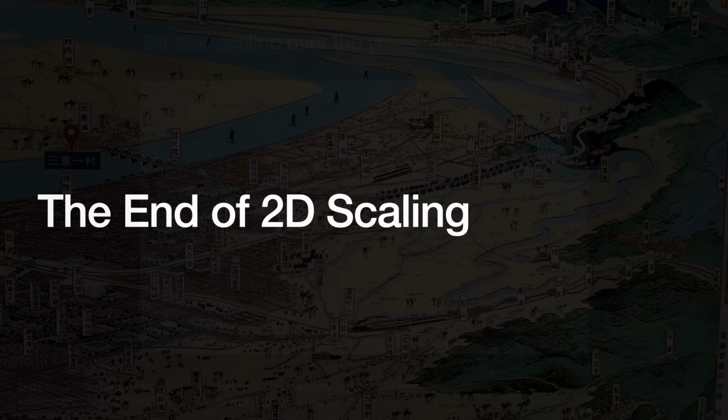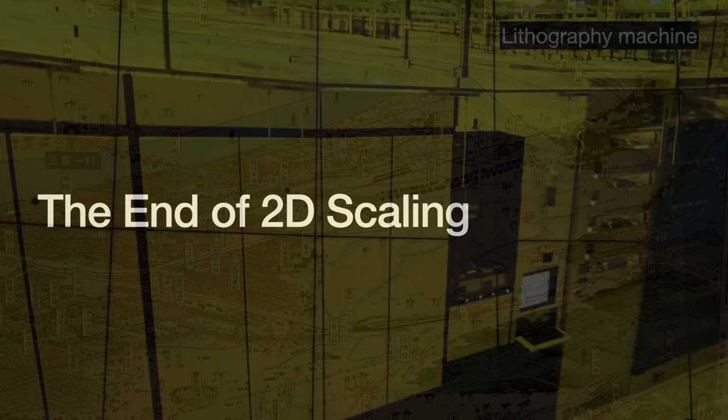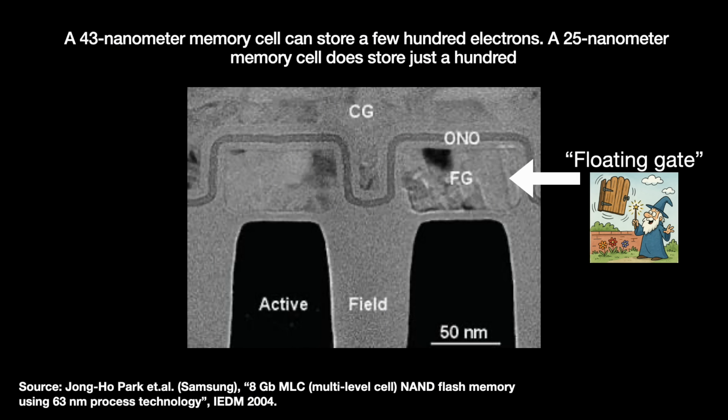This is incredible scaling, but after 20 years, these 2 major levers were petering out. The costs of patterning these smaller NAND cells were getting out of hand. With EUV delayed, fabs turned to 193 nanometer immersion and then double patterning to produce the 2D layers. Moreover, the cells were getting too small. Smaller cells hold fewer electrons inside their floating gates. A 43 nanometer memory cell can store a few hundred. A 25 nanometer memory cell does store just 100, which is kind of wild if you think about it.